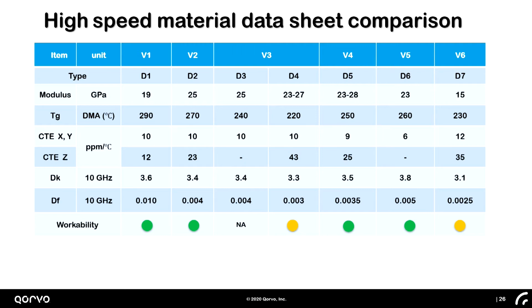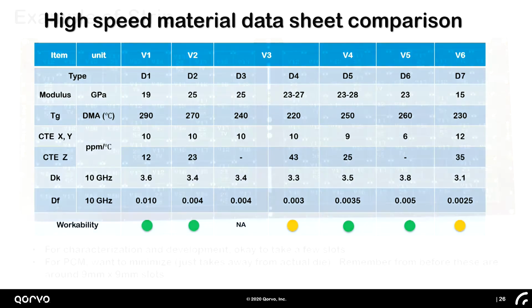And these workability things, the thing I forgot to mention on the roughness part is, if you make the surface really smooth, the next layer on top of it doesn't want to stick to it anymore, right? It needs to still stick together mechanically, because these things are going to flex. So that's another important criterion: it can't be perfectly smooth or it's not going to stick. Or they've got to do different chemistries to get it to stick better.